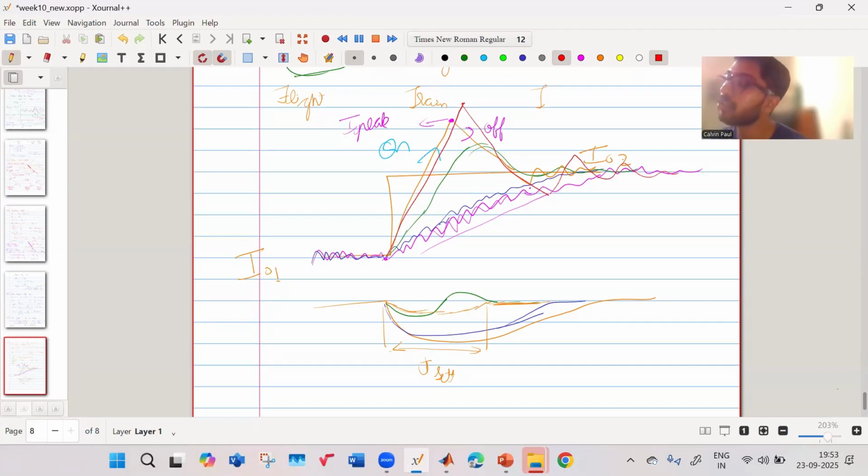So that is no longer optimal. So your time optimal is you have your fixed recovery time, you have your fixed peak current, and you have your fixed voltage undershoot. Okay. So this is your fixed thing. These calculations are unique. That is the concept of time optimal control.